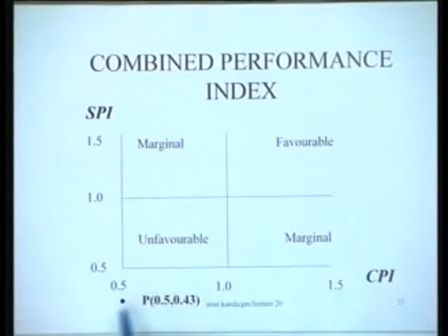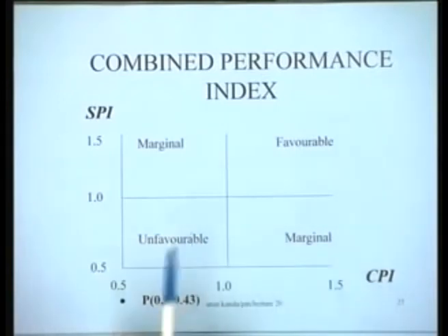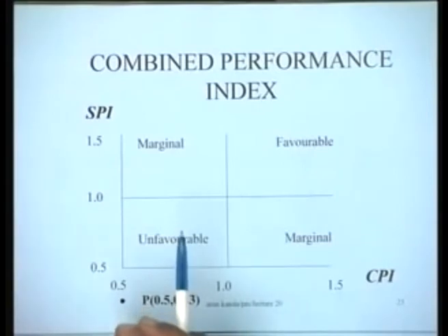So this is how we can get measures of the cost overrun and the time overrun in a project based upon the performance report of the various activities from the site, which tell us what the individual performance of the individual activities is, and then we have taken the actual figures of the money that has been spent, and these are then compared with the original plan, and on that basis we get these figures.